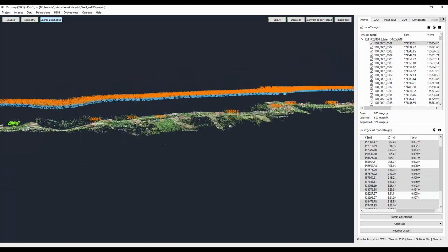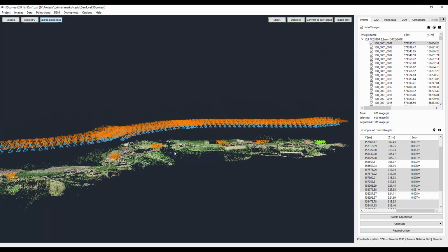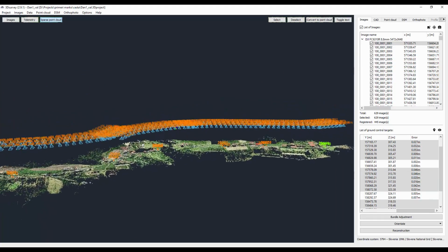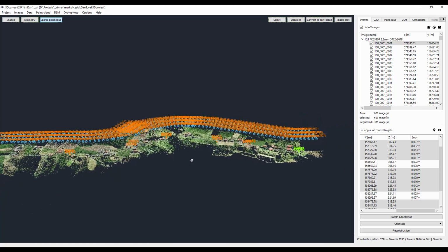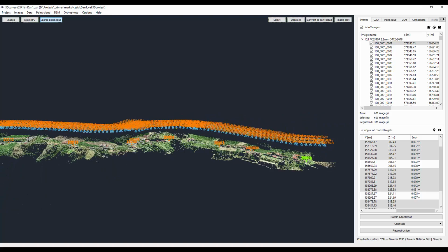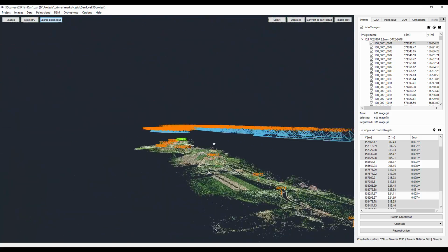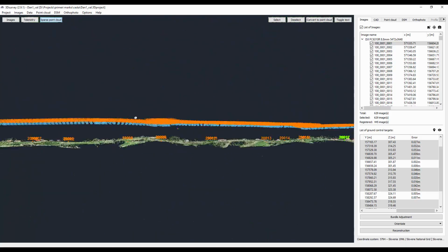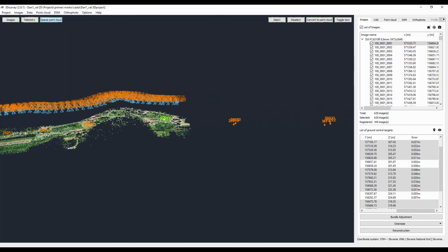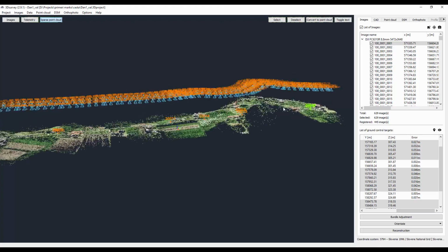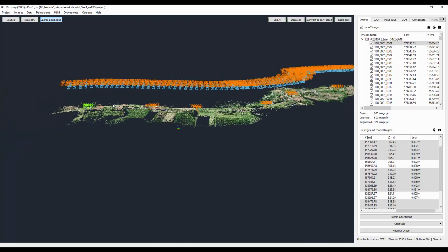Of course, the accuracy would be even a bit higher if all points were used as GCPs. The middle points wouldn't be used as validation, but for this demonstration I just wanted to show you what kind of accuracy can be achieved with very little work, because setting 2 ground control points on each side of the survey area doesn't take a lot of time.